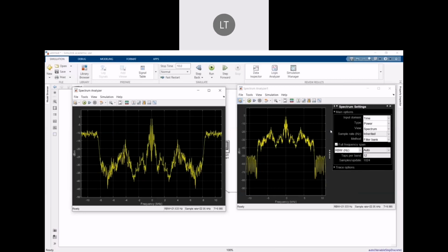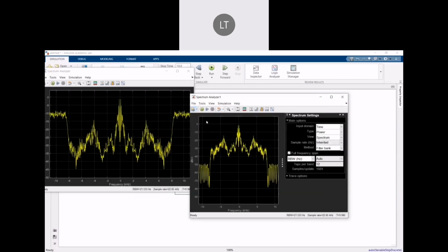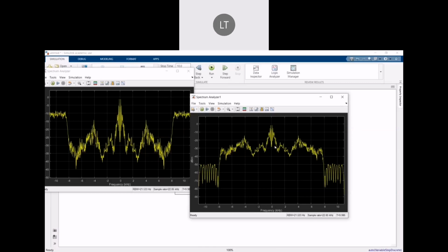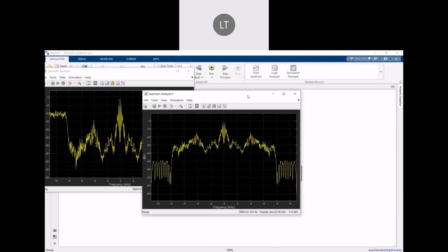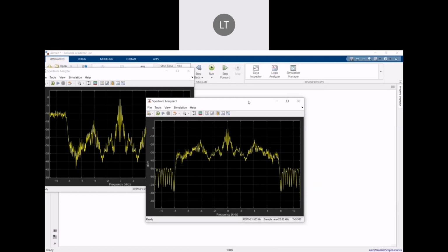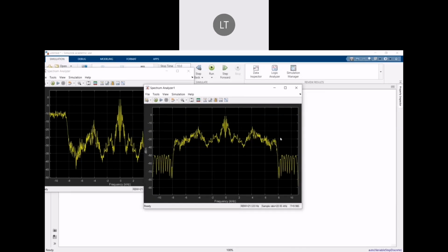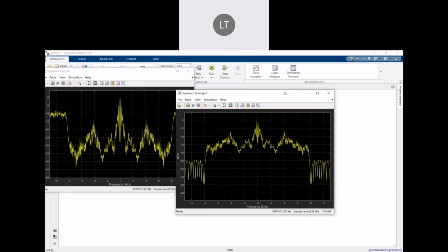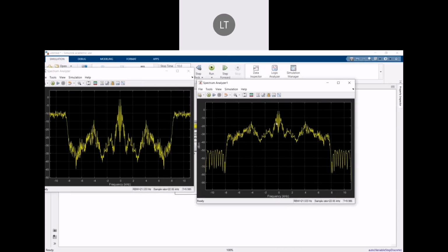So after filtering, this is the signal after the filtering, which is the low pass. Because, following the theory, the filter allows the signal to pass through within the range of the cut-off frequency. Our cut-off frequency is between about 7.5 kHz and 8 kHz.